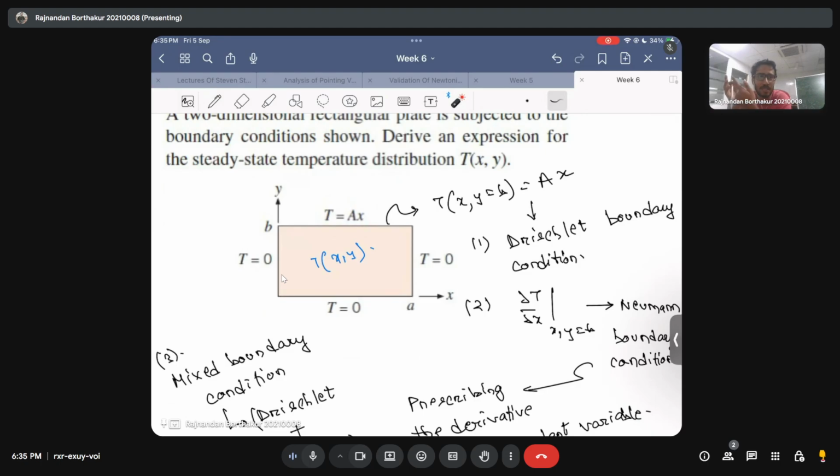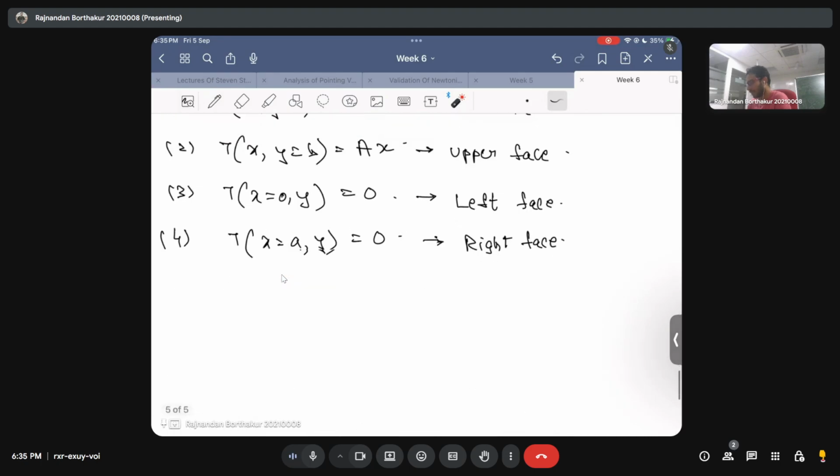First of all, as I said, it's elliptic. Laplacian problems are always elliptic, which means in order to find closed form solutions, you need to have values on all the four boundaries. Second, it's kind of an averaging function. So the temperature profile you will calculate will not exceed the values from the boundaries. Basically, it will always be in between the extremum values of the problem, that of the boundaries. That is something that I want to convey. Anyways, this is some extra information that I want to give.